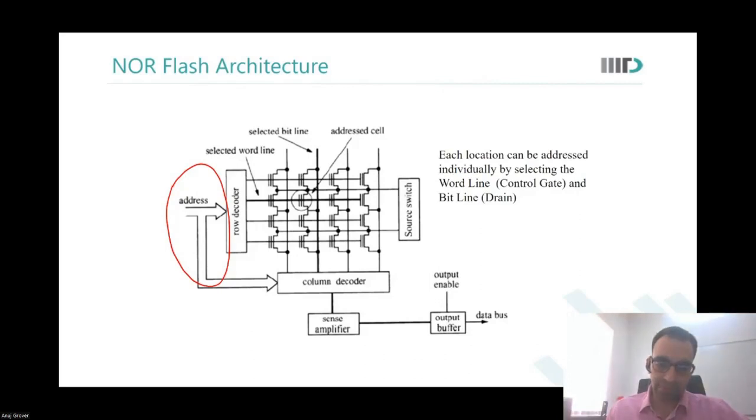Less resources. Yes. Again, this is very critical over here because flash is always off chip. If the flash would be on chip, then again, you need not have this multiplexing of row and column address on the address bus. But if flash is, how do we put it, off chip, then there are a number of pins that are involved there, and that is what needs to be taken care of.